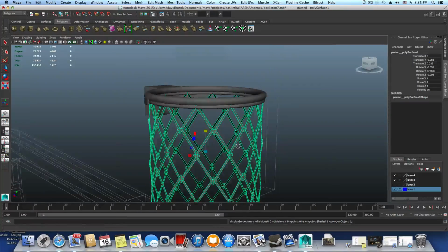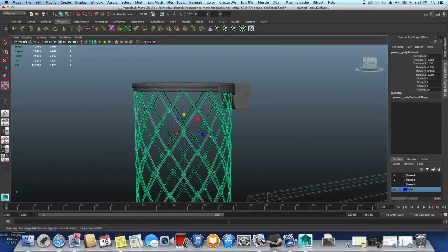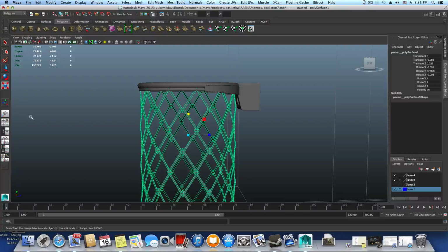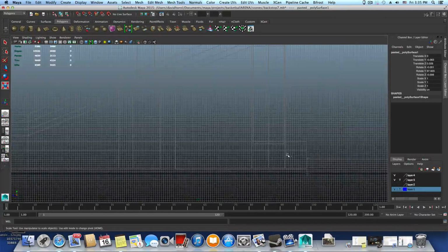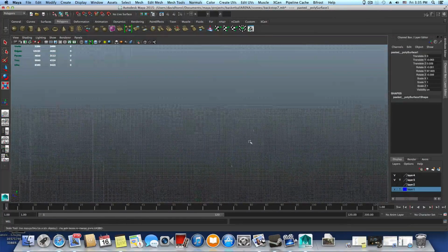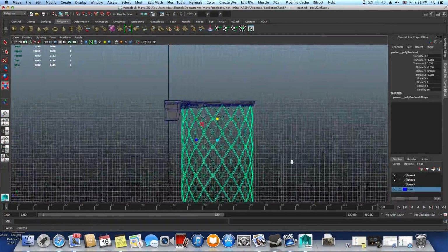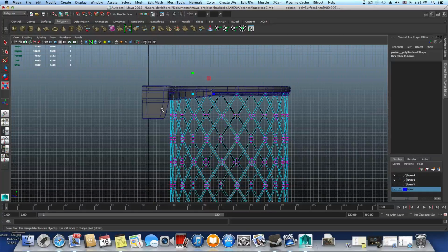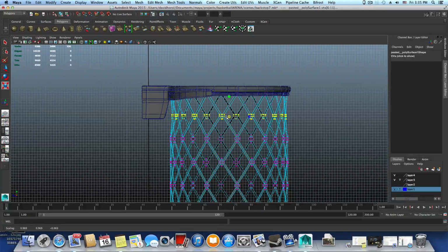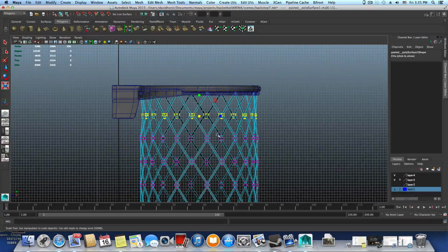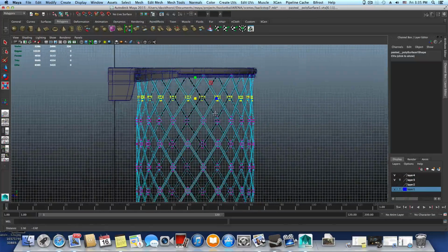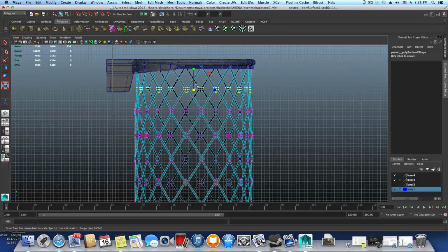The only thing I will do here is after I set it beneath my ring, I'm gonna switch to side view. Here, let's go over the net. Right click, choose vertices. Let's grab these vertices. Let's squeeze them with the scale tool uniformly that way. And these, you see, this is square, but it's not even square.